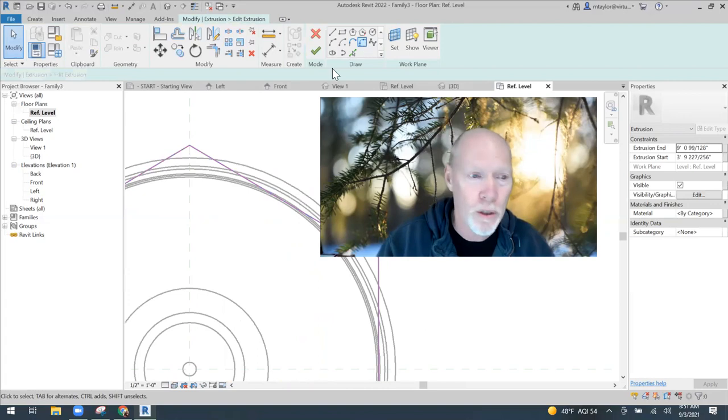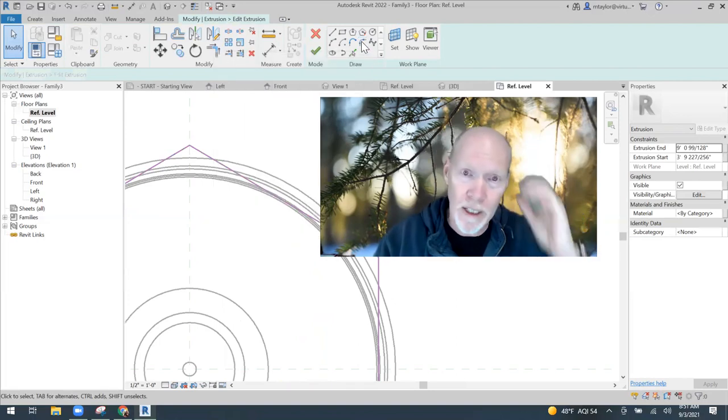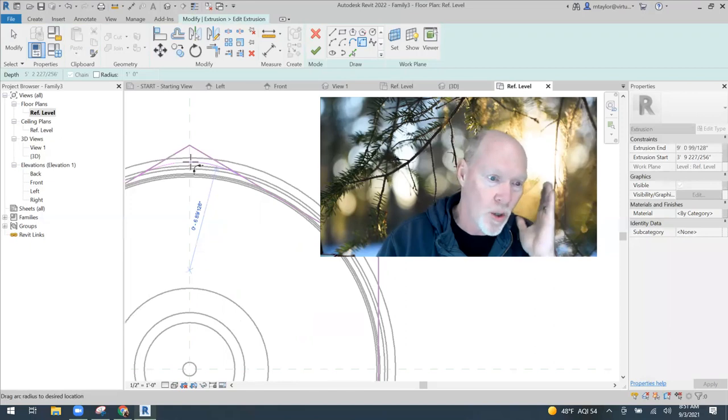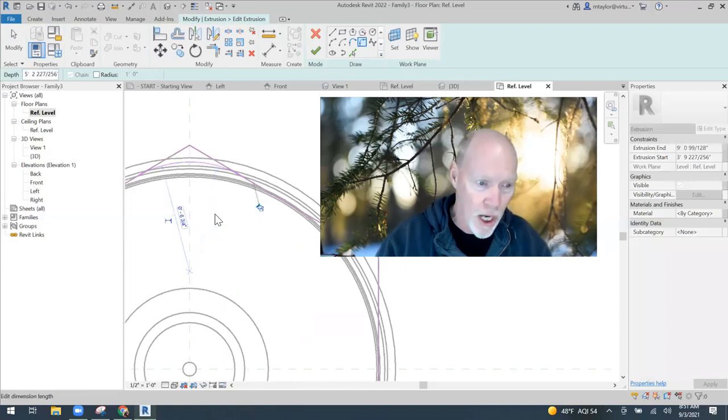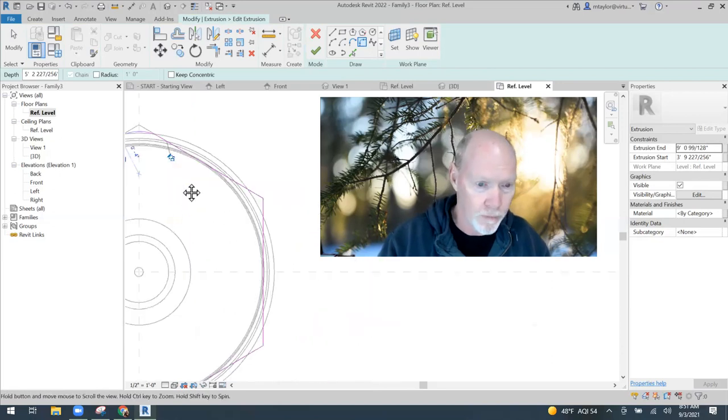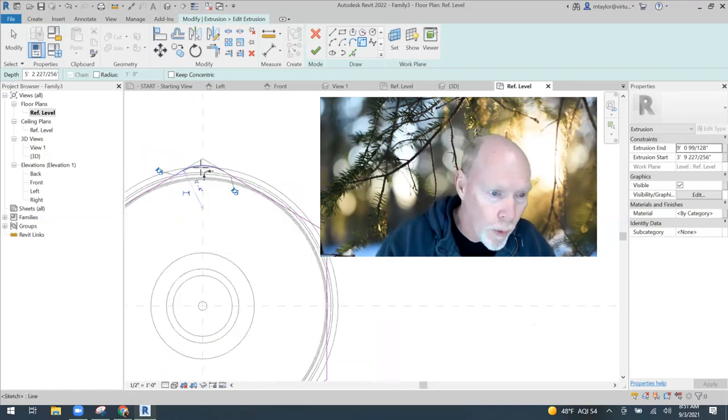And so the tool I use here to change this is this guy right here, this fillet arc, okay? Or fillet if you're cutting fish. But this is a fillet. I'm going to click that, and you just click the two sides, and then you tell it what curvature you want, okay? So I usually just place it and then change this. I'm going to make it 4 inches, okay? A 4-inch curve. Or 2 inches. How about 2 inches?